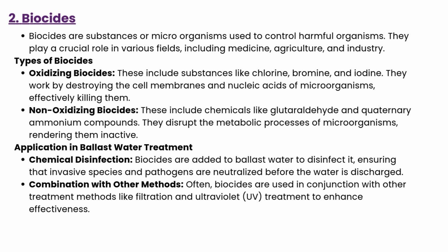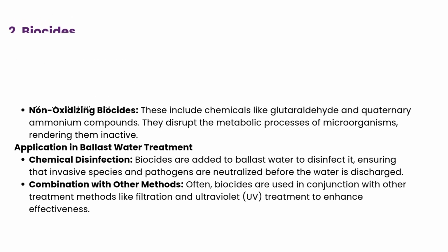Normally, in any ballast water treatment, number one, filtration has to be done, and they are not using a single technology, but at least two technologies. Either they have a UV treatment system, and also they are using biocides, either oxidizing or non-oxidizing biocides, and it is getting treated.